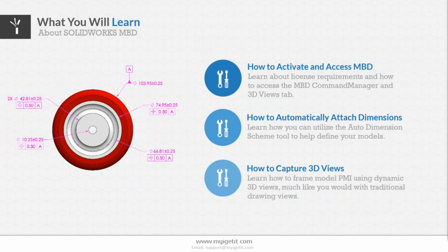And we'll again learn how to capture 3D views to represent all that PMI, much like you would traditional drawing views, except 3D views are dynamic, so you can rotate them, zoom them, and inspect them a little bit better than 2D drawing views.